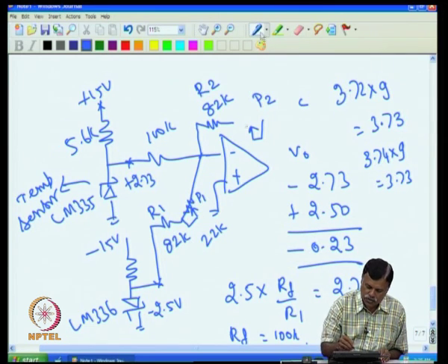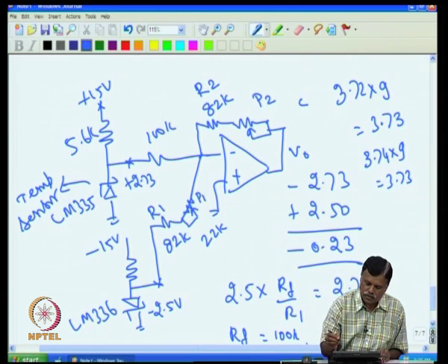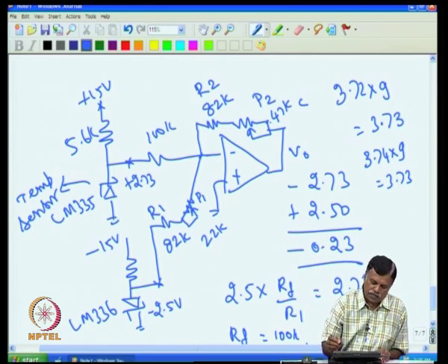Okay, what I do is I take P2 a little higher, so that my adjustability is better. So, I can put, for example, P2 as 47 K, and then this is fixed 82 K. So, I can adjust now up to 129 K at one side when the potentiometer is maximum; when the potentiometer goes down, I will have 82 K. So, now what I do is I will put this one at 100 degree C and adjust P2 to get 1 volt.